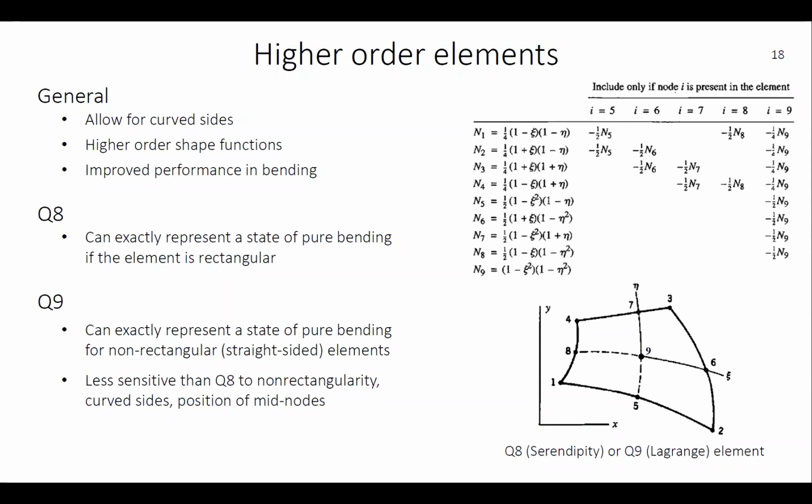And they allow for curved sides since they have higher order shape functions. So it's easier, firstly, to fit these elements to an arbitrary geometry. And also they have improved performance under bending-like problems, which I will illustrate with some examples.